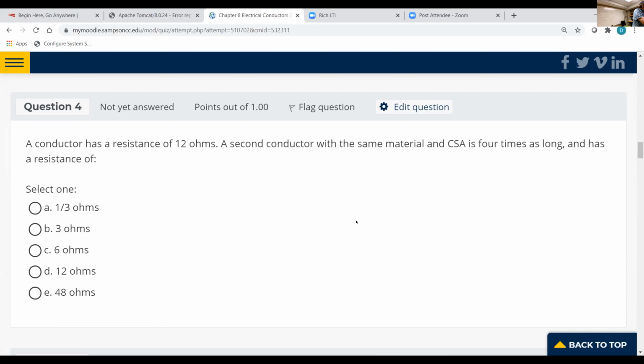That's why it's so important in hog houses that when you're running them long runs, chapter 9 is going to be a real eye opener for you, Jamie. You're going to be a guy that can go out there and tell somebody, contractor up front, if they're not doing this. You can plug some numbers into a formula on footage and amp requirements for that farm, and it's going to kick you out a CSA that you can use to get a gauge off of and be exactly dead on for the wire for that long run, and you will not have a voltage drop issue, guaranteed. You won't. No embarrassment. You ain't gonna have to go back and pull new wire.